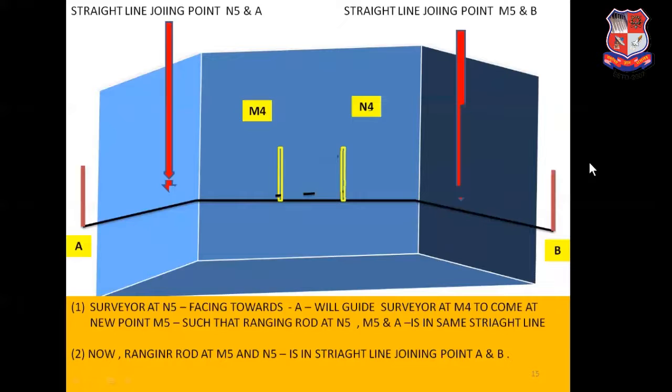By repeating this process, a time will come when ranging rod A, ranging rod M, ranging rod N and ranging rod B come in the same straight line.